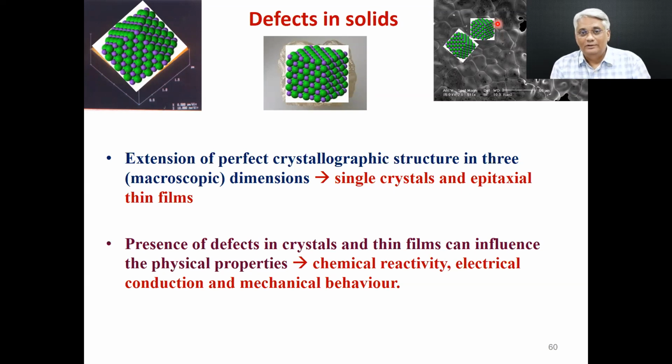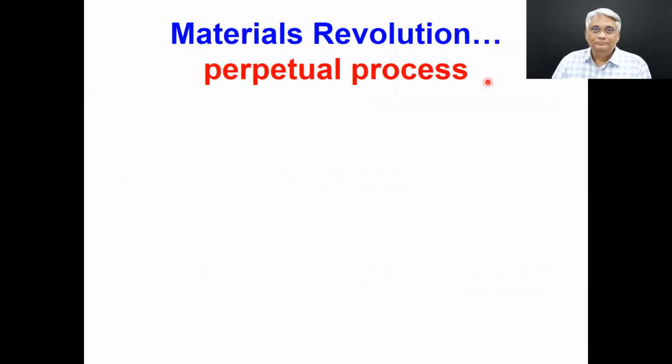That's because of additional grain boundary resistance, right? Grain boundaries are more resistive because you have loosely bound atoms. You have terminated crystal structures. It all depends on the grain boundary widths. If you have a polycrystalline thin film, the grain boundary widths are much narrower compared to the grain boundary widths in a polycrystalline bulk material itself.